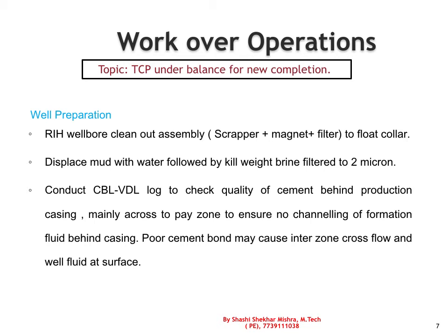Once the wellbore has been cleaned to the bottom, we displace mud with water till we get a good NTU, that is normally less than 30. Once we have clean return water, we displace the well with kill weight brine, which is also filtered to 2 microns.